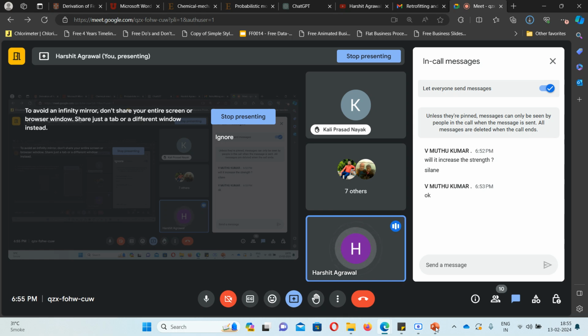Once you have applied the spalling repair, if you see that this leakage is a constant problem and it will occur again, we can coat the surface of the concrete with a sealer compound or a protective coating, so that there is no water ingress in the concrete and the strength or the performance of the concrete is restored. So, in the discussion ahead, we will see that case.